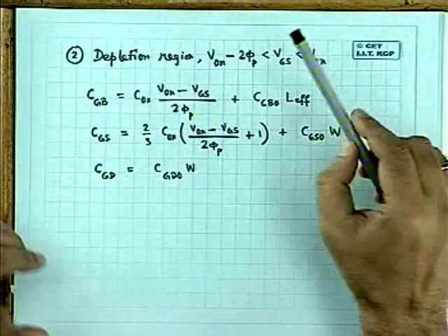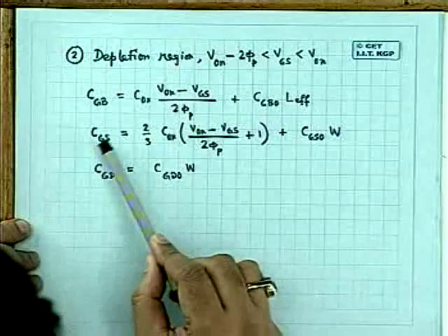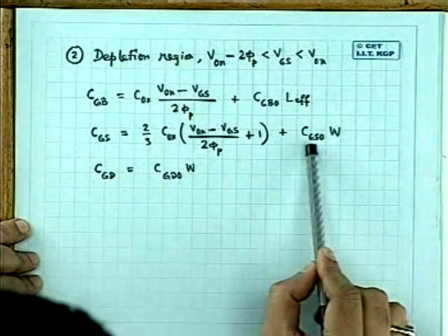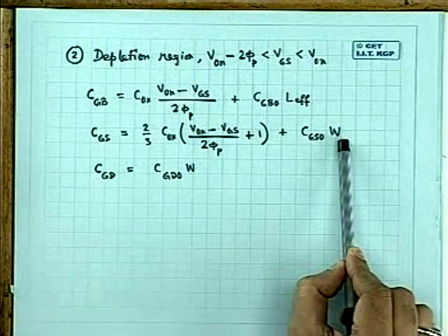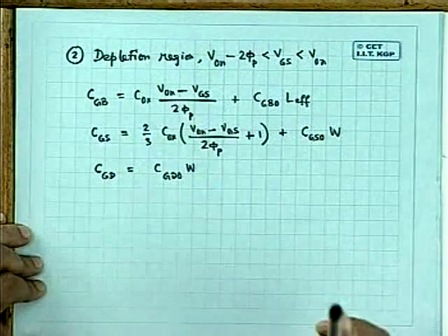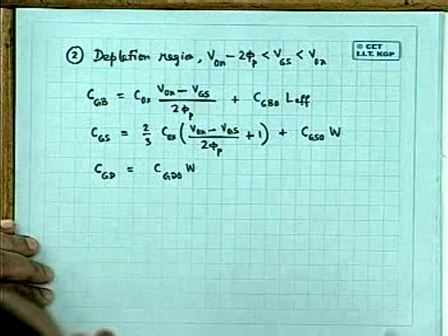But this weak inversion layer electrically extends the source from the source end towards the drain. But because it is below VON, the full channel is not total. So what is going to happen as a result is that the CGS value, in addition to the CGSO, which is the overlap capacitance, has another component added, which is this. It is modeled like this. There are some theoretical derivations behind them, but ultimately the simplified form is like this.